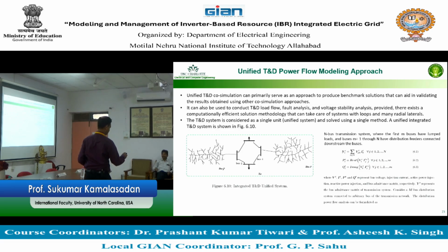I'll give you a hint. Okay. You look at this equation. This equation needs to be solved if you want to run a power flow. Let's look at this equation. V equal to summation of Y times I, right? Or the other way around, Z times I, or V equal to. So what is important? Before you find V and I, what do you need? Y. It's the first thing you develop in a power flow, and in a transmission network power flow it is called Y bus.